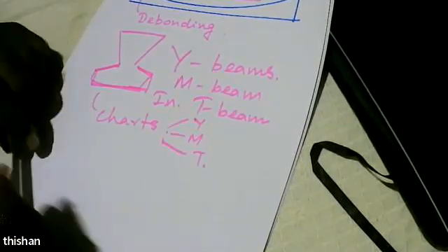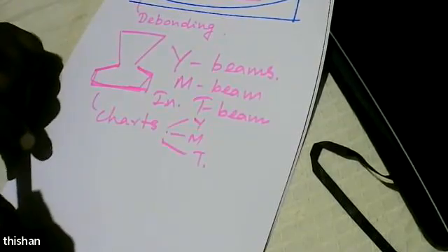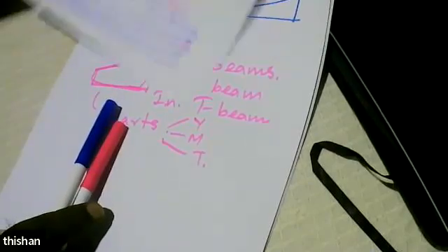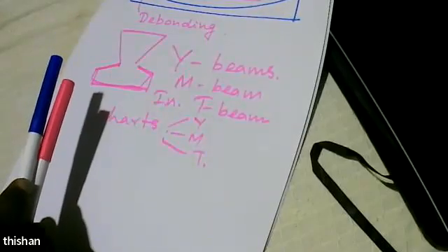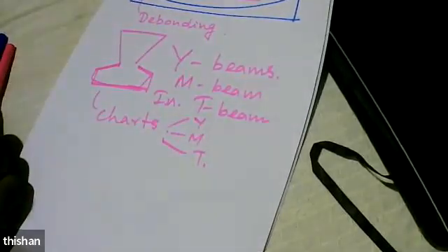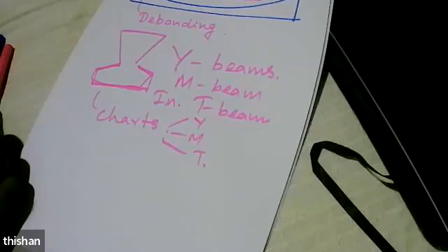So it's not a difficult task. Once we come up to this level, either pre-tension or post-tension, we have to do many other calculations, like calculating the losses as shown. The R value of 70% is a valid assumption. Then you also have to check for shear, and you can check for deflections. Those are standard checks that you have to do.